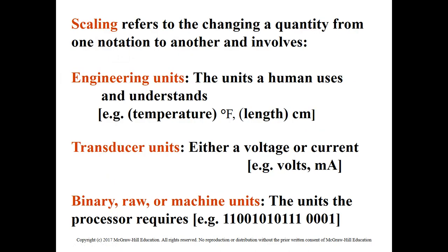So we have some scaling here, because as we said when we studied the transfer function, some analog inputs are from 0 to 10, some from 4 to 20, from 0 to 20 milliamps, and so on. In order to do scaling, we need to define, for example, the minimum value and the maximum value, and based on pre-calculated values, we need to define the highest and the lowest values.